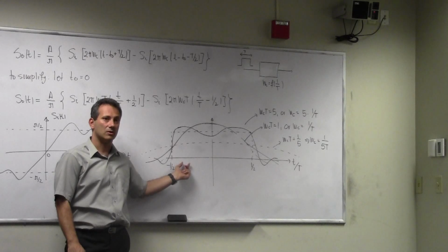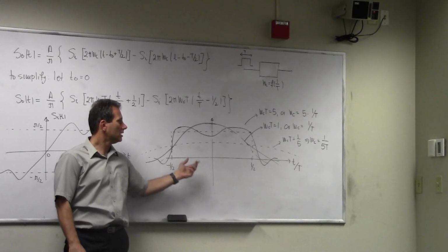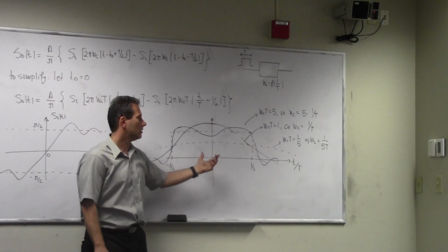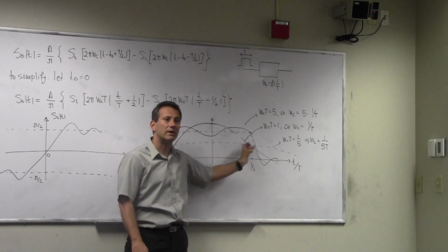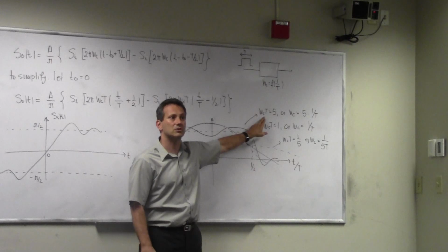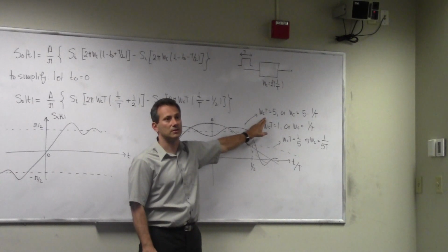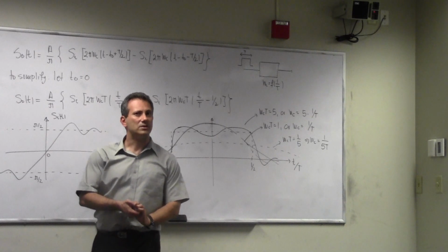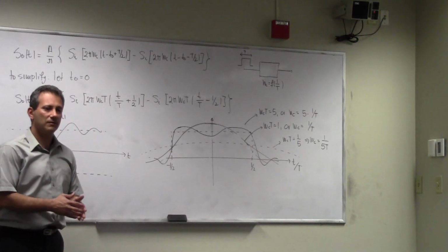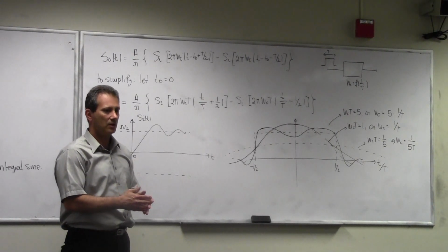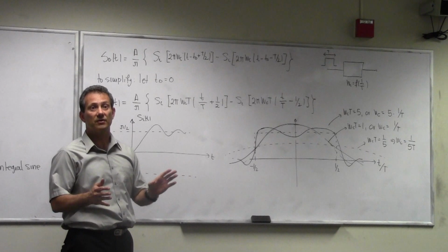So the consequence of a band-limited transmission is this dispersion in the time domain, and the fact that now your transmission in a time interval of a duration T results in energy that is spread over multiple T in the time domain. And the smaller the bandwidth relative to the inverse of your bit duration or symbol duration, the larger the dispersion in the time domain becomes. Okay? So now we see what is the fundamental thing that we're fighting with here. It's self-interference, self-induced interference.